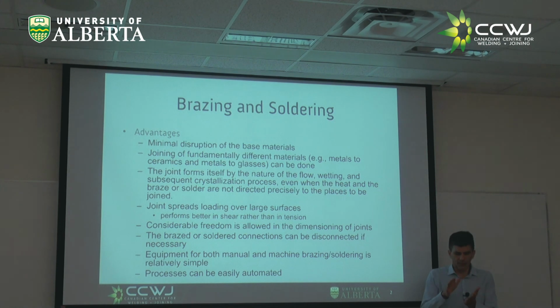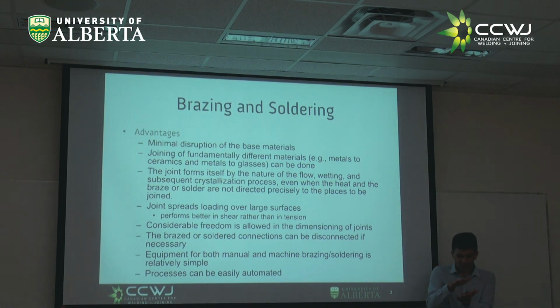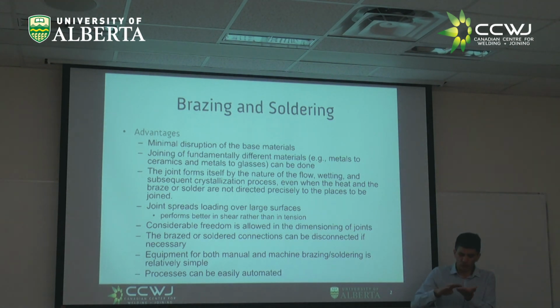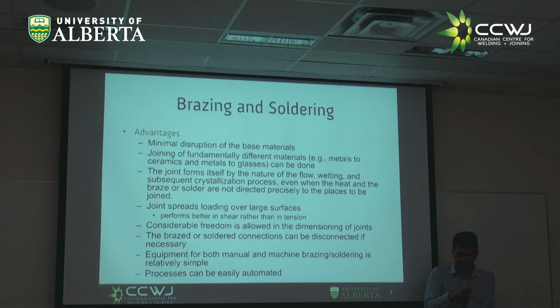And you do the same. You put the two parts together in brazing, and they are very, very close, and they are wetting, right? Your braze wants to touch this material being brazed. And so it starts to pull through all these cavities and goes by itself, right?